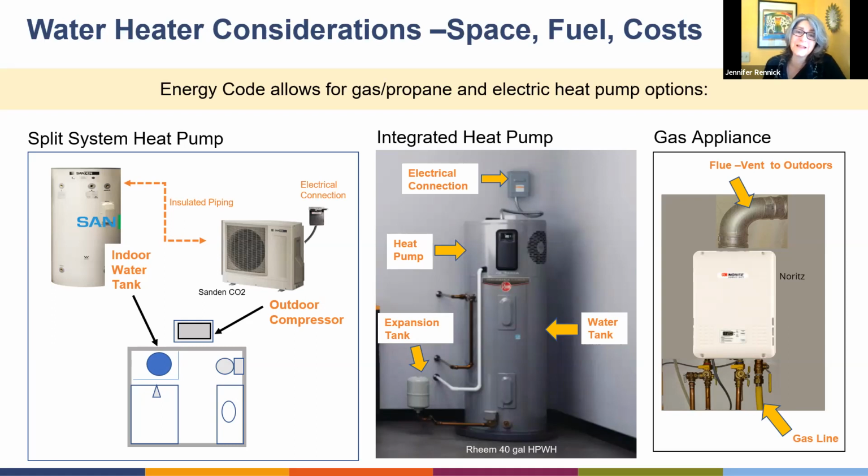And this flips that around. So the roundish looking little louver vent on the right of that tank would actually push out the cold air and put the heat into the hot water. It does require electrical connections, and it does require a certain amount of volume of space to work. If you don't have that volume in your ADU, you can duct it so that that cold air does not go into the small ADU, but goes outside.